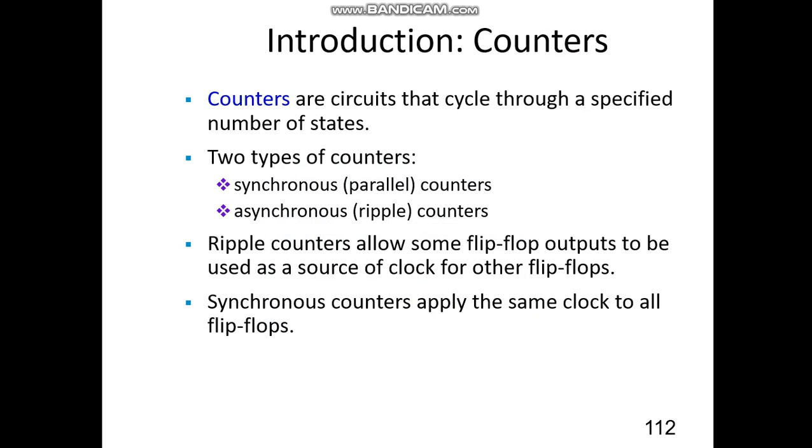For example, in a circuit, if you want to turn on a motor after 9 seconds, you have to create 9 seconds of clock pulses. For example, if you fix the value 100 as the maximum count, it will be reduced 1 by 1 until it comes to 0. That is a down counter. If we want to count clock pulses, we use counters.